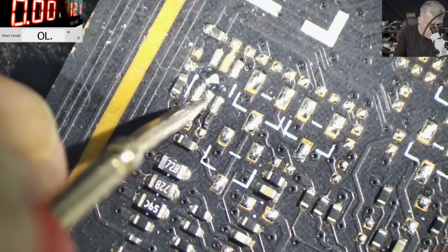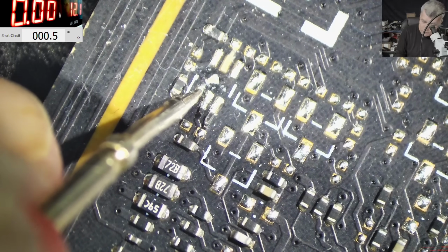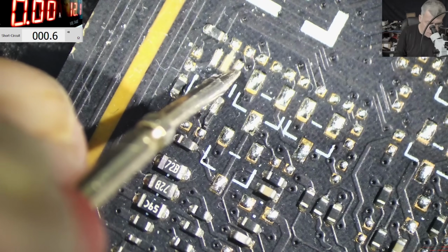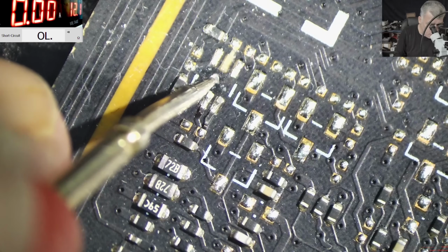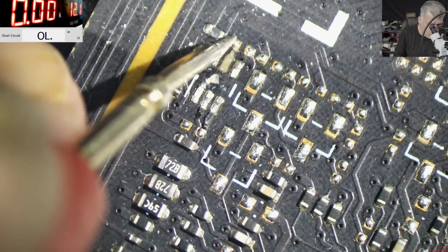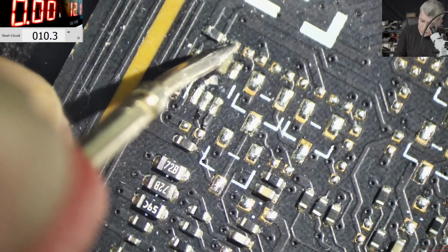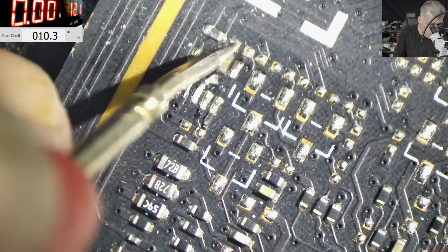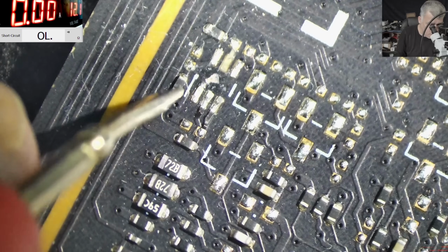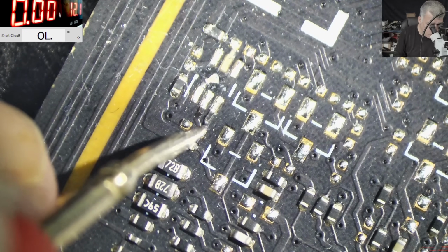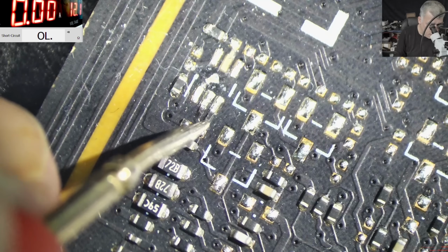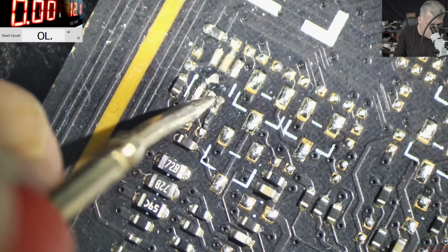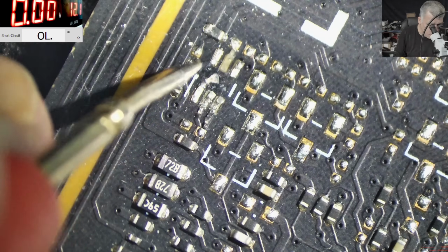So the other pins are, this is ground. Okay, this is ground. So you have two grounds. And this is something else. No, this is 10 ohms. It's something which has 10 ohms. Oh, those are together. Okay, that's bad. So probably this is a power track because those two pins are together.